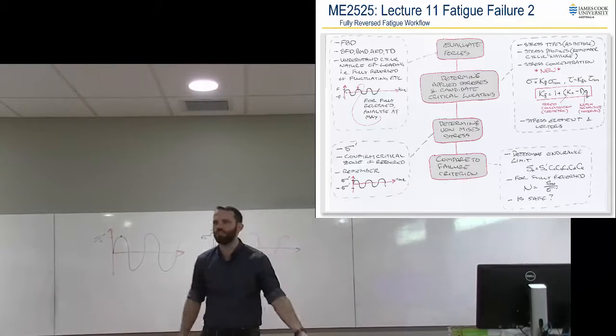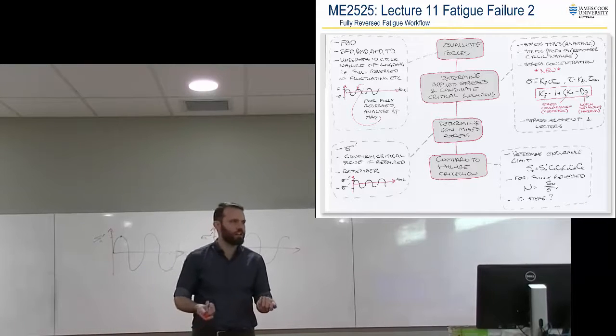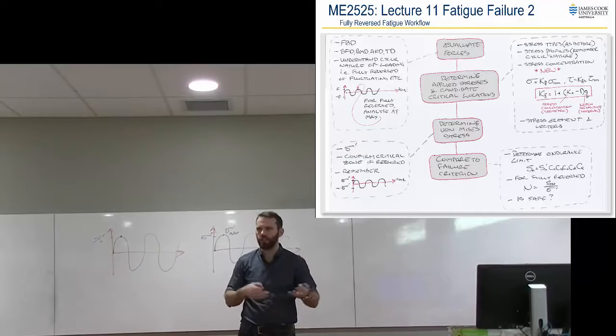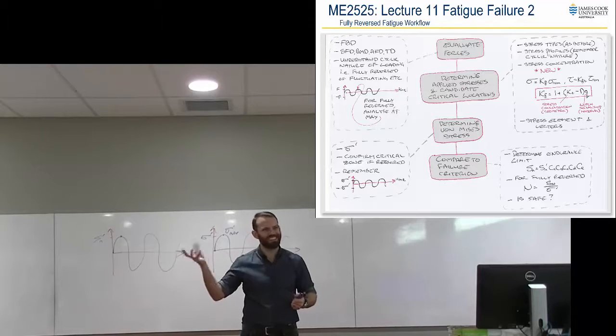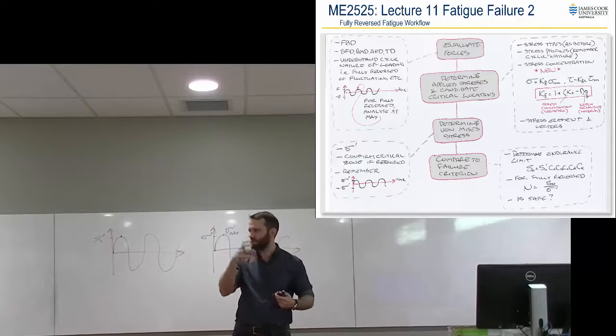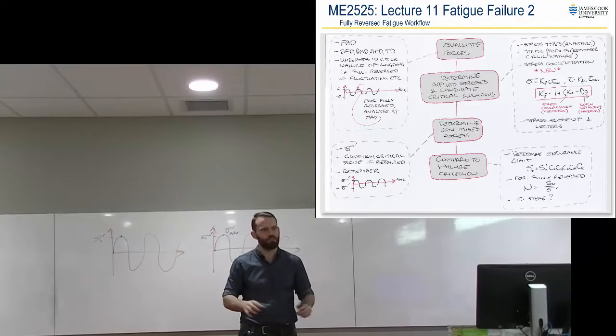Last year we used to do this on the endurance limit modifying factor, alright? But that gets a bit confusing because you guys know that you can calculate a different stress concentration for each type of loading. So bending, axial, torsion. And when you only have one factor on the right of the equation, it gets a bit confusing which one of those you use. Whereas on the left, we can apply this to every single element of stress, every single vector of stress for the particular components appropriately, and it works out fine.